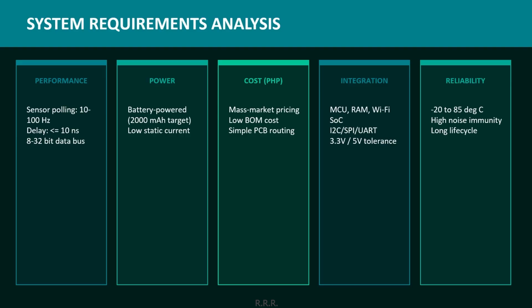Fourth, integration. The logic family must play well with our other components. Microcontrollers like the ESP32 or STM32, flash memory, Bluetooth and Wi-Fi system on chips, and communication protocols like I2C, SPI, and UART. And fifth, reliability.